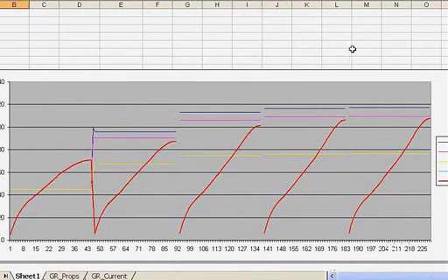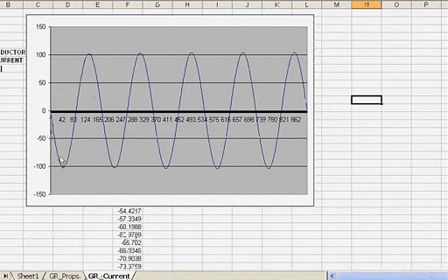So those results, if you took this further, you would do what I did over here, and I actually combined all the quarter cycles, reversed them, and I made this graph here generate the actual current that was flowing in the winding, because I wanted to see if the device was stable as it got hot. And I deliberately made the air gap large in this case, and that is the effect of diluting or diminishing the nonlinear effect of the ferrite as it gets hot, because the air gap dominates the impedance of this device.